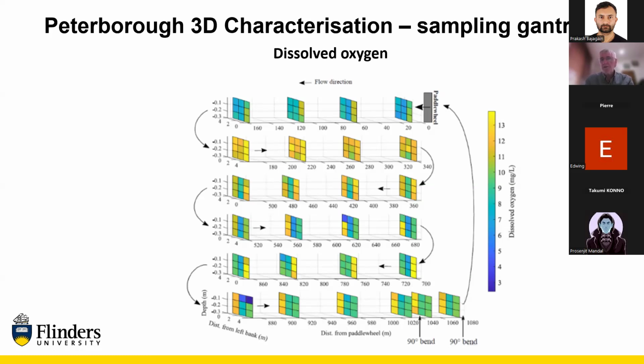So the dissolved oxygen might be, at 7 o'clock in the morning, 7 milligrams a litre. And then by 3 o'clock in the afternoon, it's 20 milligrams a litre. And then by 6 o'clock in the evening, it's back down to 7. So it's naturally changing over the day, and yet we're trying to measure differences between, is there a difference between here and here? And it takes us 12 hours to do the measurements.